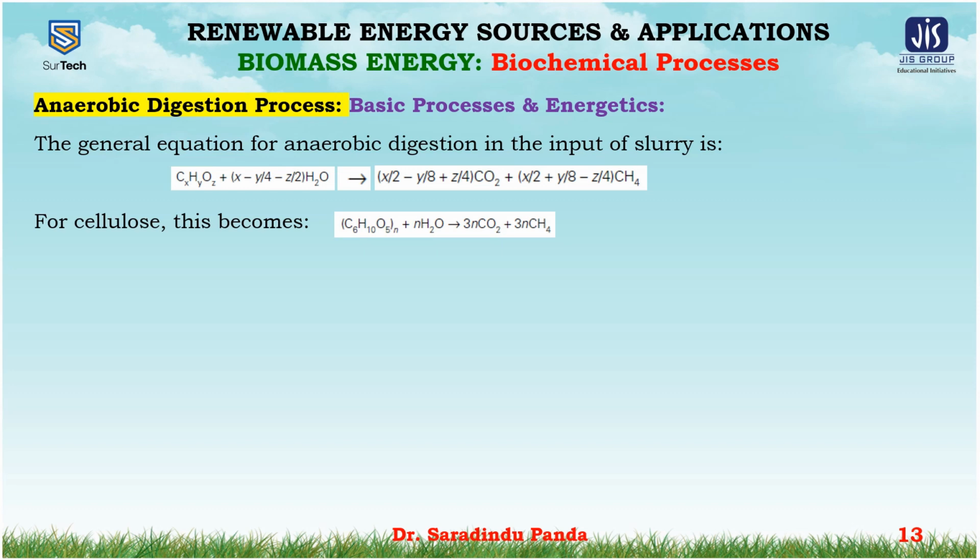This is not sufficient to significantly affect the temperature of the bulk material, but does indicate that most enthalpy of reaction is passed to the product gas. If the input material of the slurry had been dried and burned, the heat of the combustion would have been about 16 megajoule per kg.